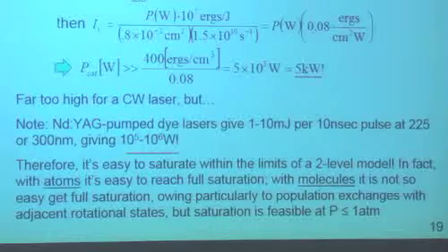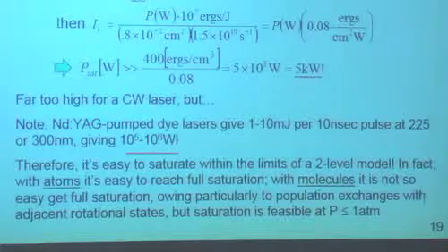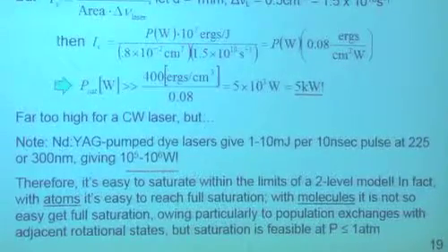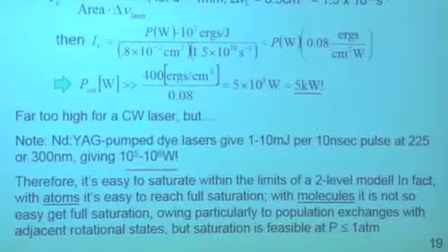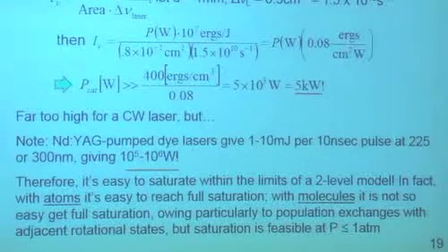Typically to do a successful PLIF experiment, you'd like to have 1 to 2 millijoules. The high repetition rate people are doing this with 0.1, 0.2, 0.3, not looking so good in the signals. But if you use a modest system and I calculate the power, all of a sudden it's looking attractive again. Hold it, the instantaneous power is a megawatt.